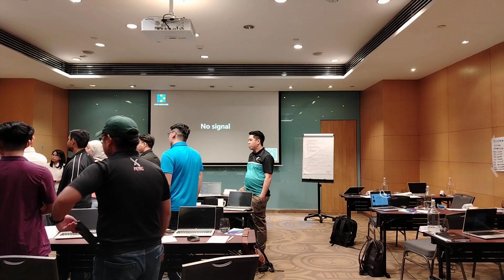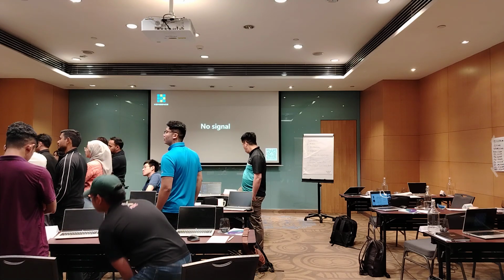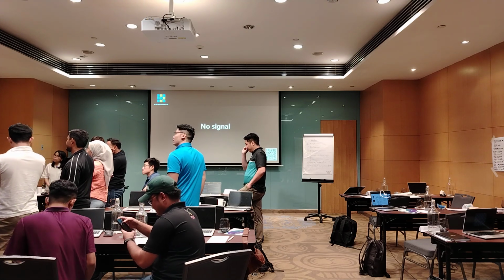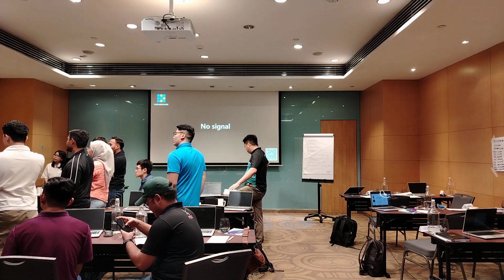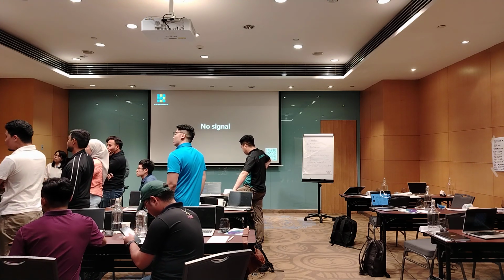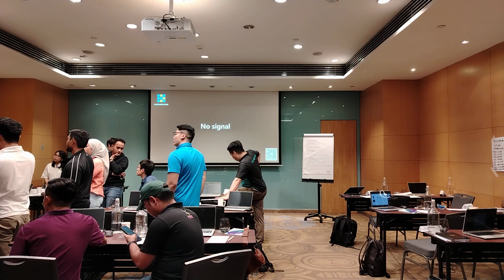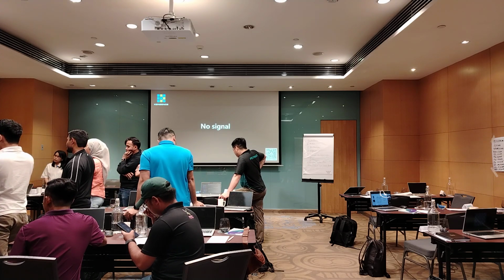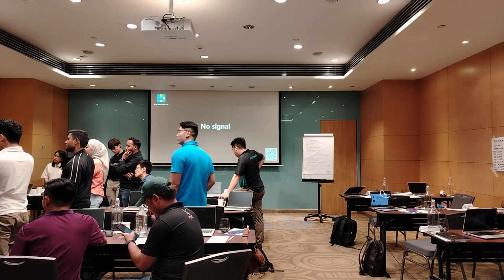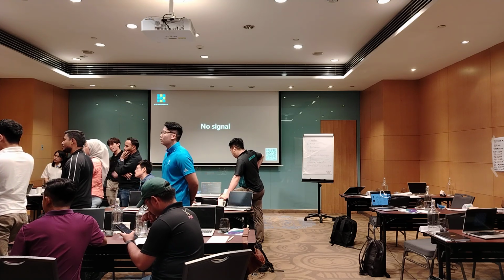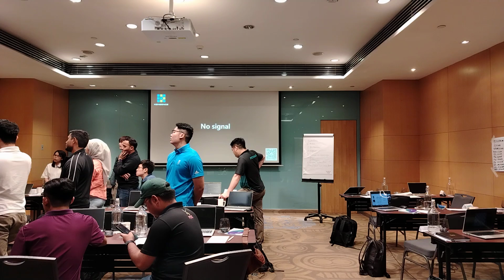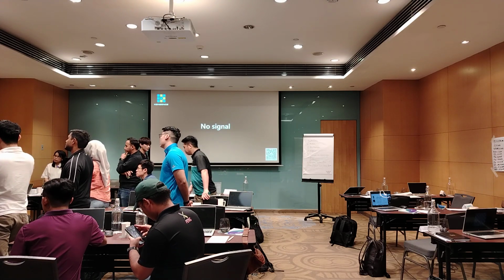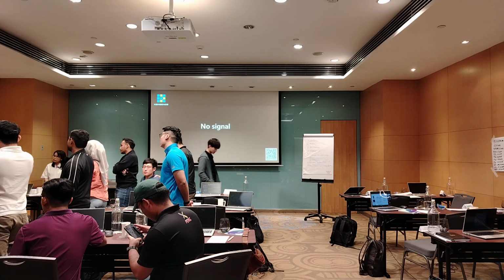I want to ask, if at the start of installation of the seal there is, let's say, an alignment problem. Yep. So maybe it depends on the pump also, right? Yeah. Don't have any spares. But if there is a spare, we can just do the realignment back, right? Yes, exactly. But you have to ensure the alignment five-point check. When do you usually do alignment?